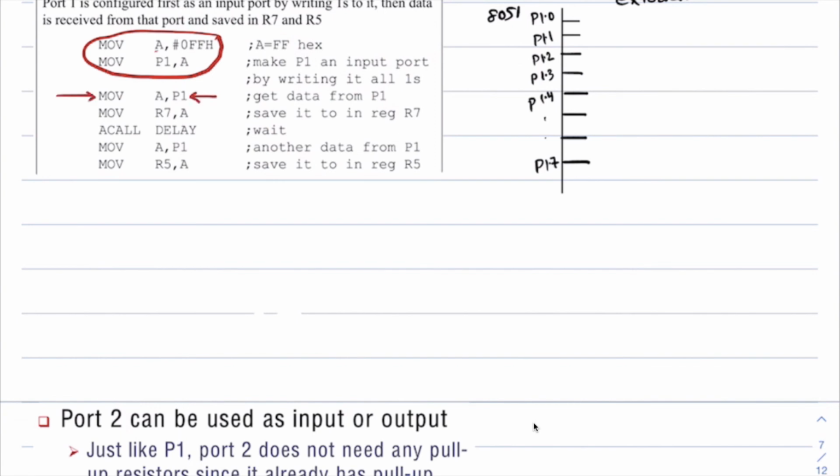So when I am taking the data, assume that the data available in this port 1 is 0 1 1 0 1 0 1 1. It may be like 0 means it is a ground here and 1 means it is a VCC. So the devices are configured in such a way that externally it could be a switch or a sensor or anything. It is giving rise to this data on this port. So what is this data? P1.0 to P1.7 means it is 1101 and 0110.